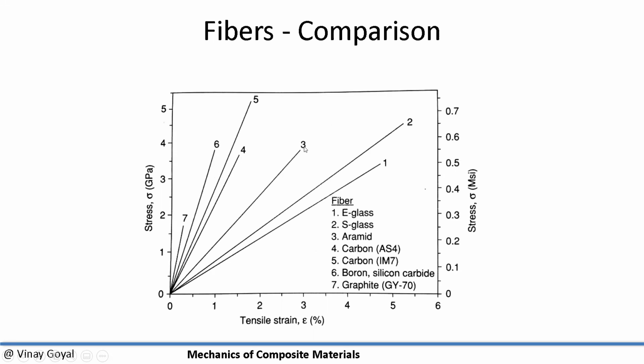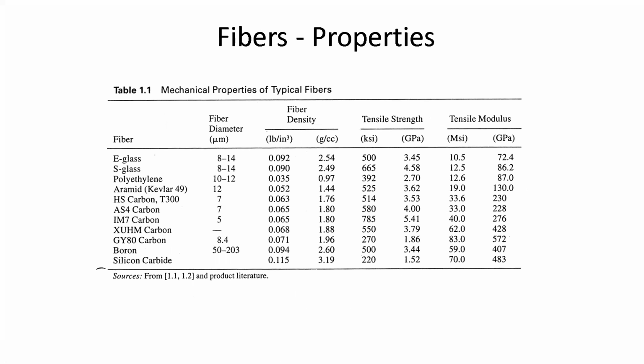Look at that, way above everything else out there, very nice stiffness. You go to boron, much higher stiffness, and then you go to graphite, way higher stiffness. But look at the strength, it keeps dropping. So there are trade-offs, and you have to look at what you need for your application. In some cases you don't need the strength. What you need is stiffness, and so you want to balance that during the life of the program.